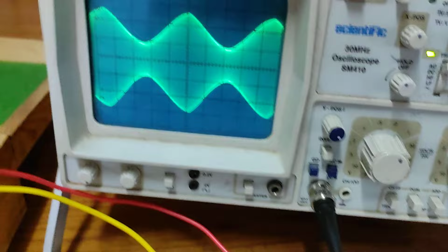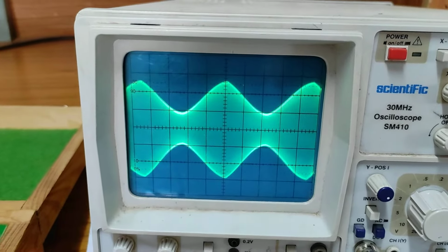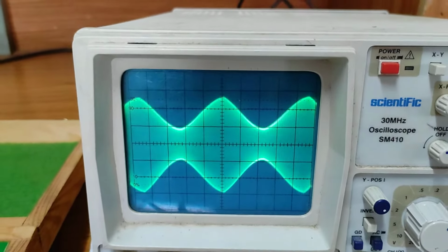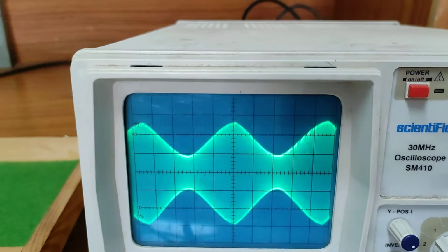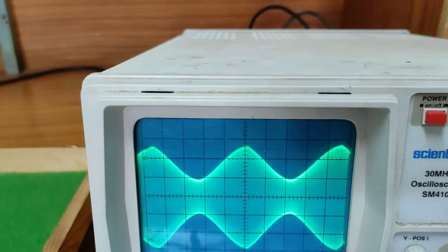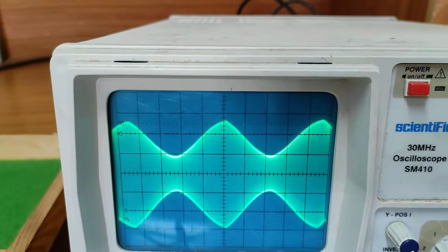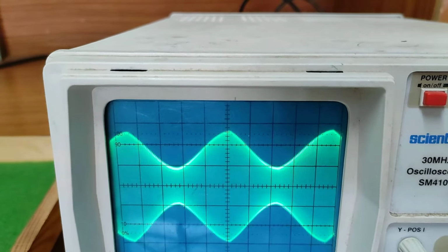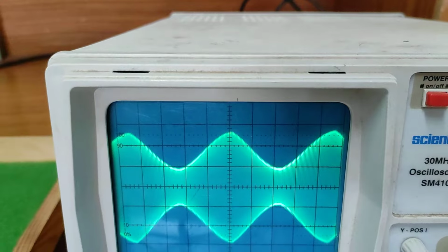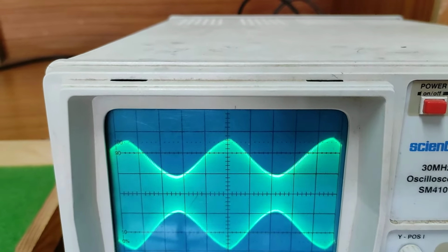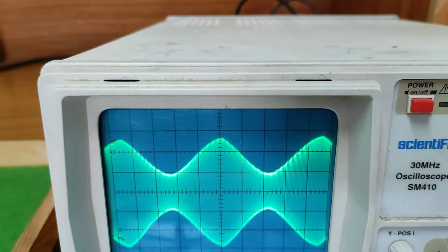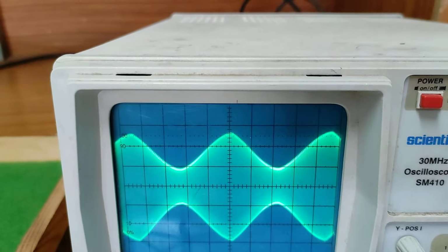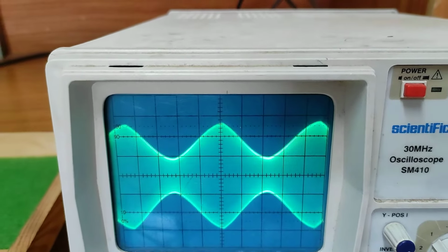So in this case, the modulation index value is 0.5, and I already told you that if the difference between V minimum and V maximum is very small, then you will get under modulation. If the difference between V maximum and V minimum is very high, then you will get perfect modulation. And for the case of over modulation, both the envelopes are overlapped together and the polarity of V minimum changes.